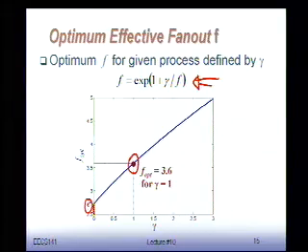And that's a very famous number because it says if you want to optimally size a chain of gates for minimum delay, what you have to make sure is that every gate drives 4 gates. The optimal fan-out is 4. And remember way back when we talked about propagation delay analysis, that typically we're always going to use a load of 4 for inverter. That's where it comes from. It is the optimal number. It is what is going to minimize your overall propagation delay.